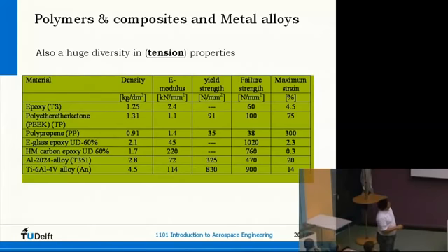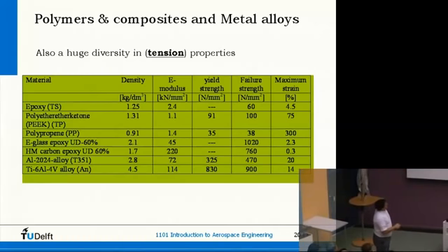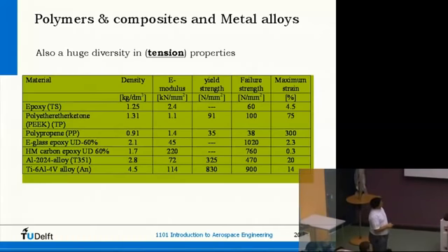And when you see the Young's modulus and the strength, and you compare that with the aluminum values here, you see what I meant when I said these materials have very low strength and stiffness properties. PEEK is a thermoplastic material. Polypropylene is also a thermoplastic material. And you can see all these materials have low values for strength and stiffness.